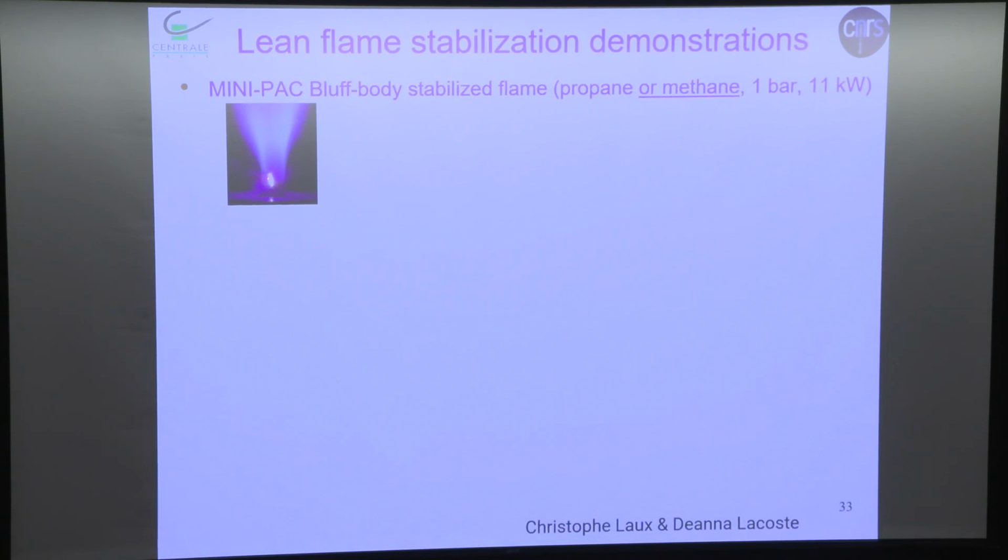The idea is that they have a nozzle, and they put in an electrode and form a nanosecond or radio-frequency plasma, and it becomes a flame stabilizer, so that the plasma can continuously supply radicals and heat so that the flame will not be blown off. What they show is that the extinction limit was reduced by 10% with a plasma power of 75 watts. It's very moderate.